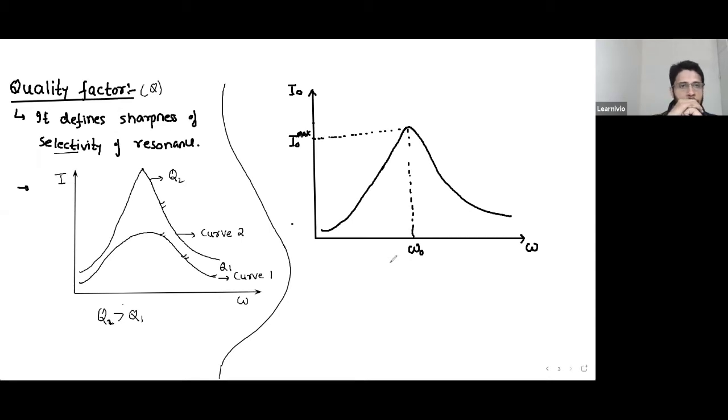Why not? Well, both are radio sets. Both are selecting frequencies. But using the radio set that you use in a car, you cannot select the frequencies which basically the police is using. There are many reasons. One of them is every radio set has a frequency range in which it works effectively. It is designed to work in that particular frequency range. Beyond that frequency range, your radio set does not work effectively. You cannot use your radio set beyond the frequency range for which it is designed.